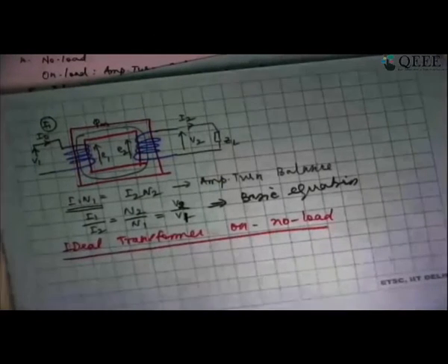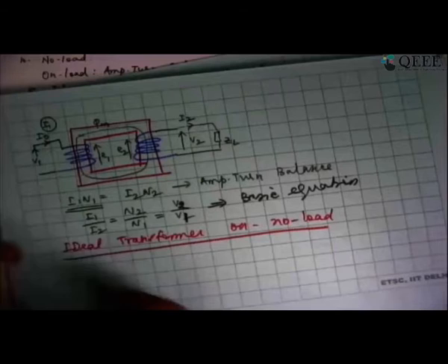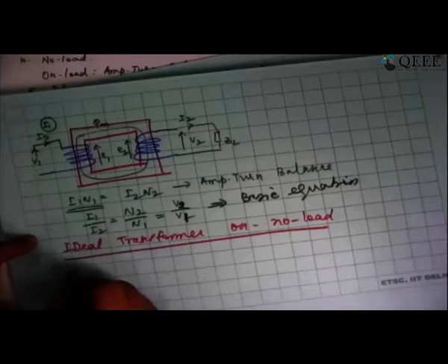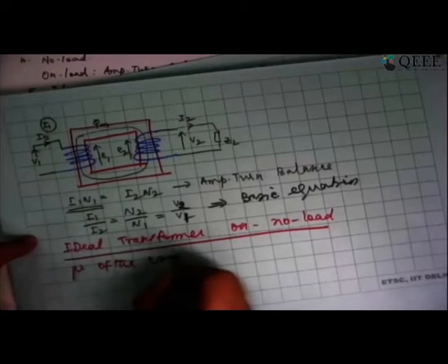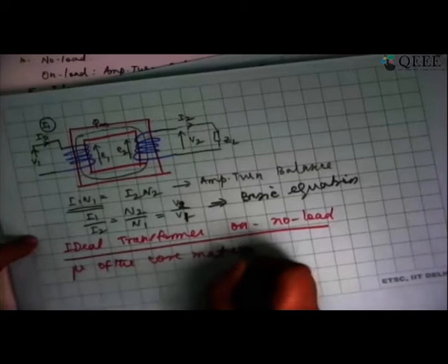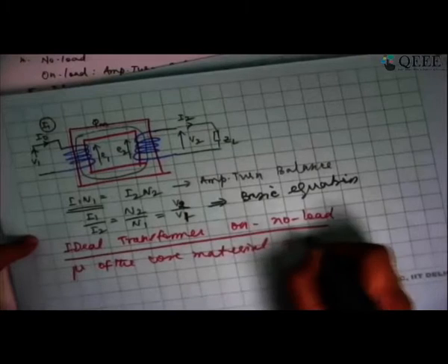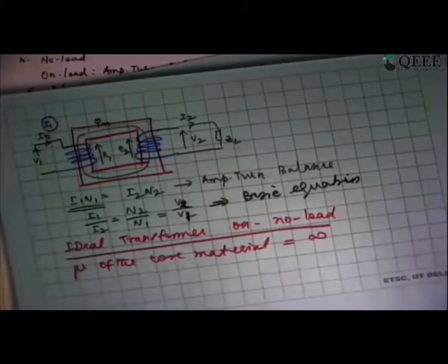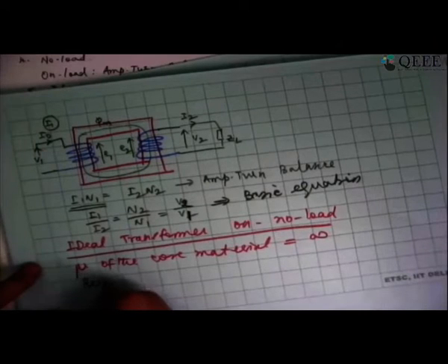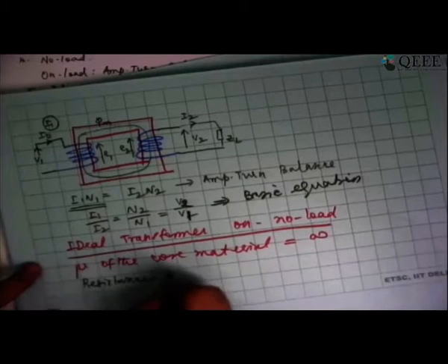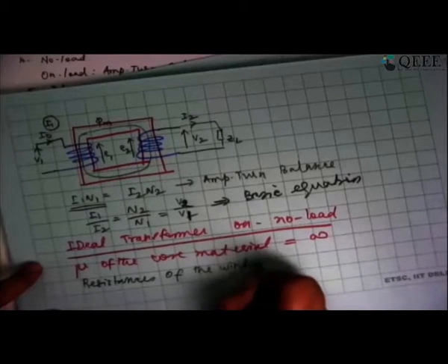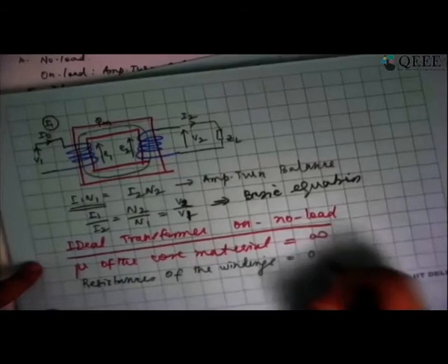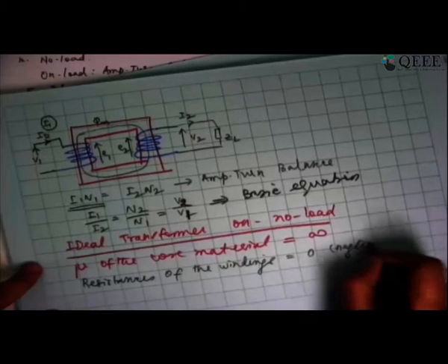Under no load condition, I am essentially looking at the permeability of the core material being equal to infinity. I can also say the resistances of the primary and secondary windings are negligible or zero.